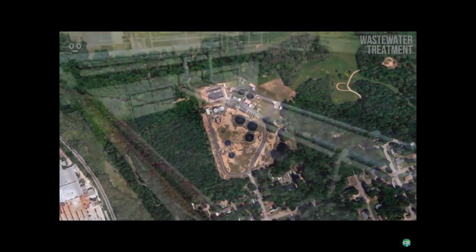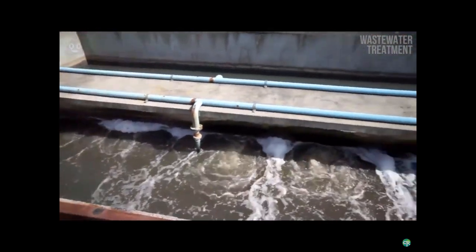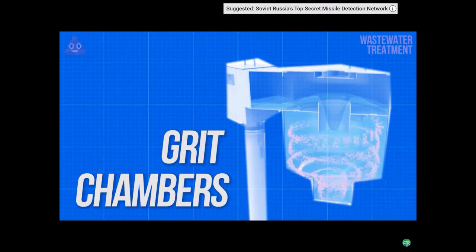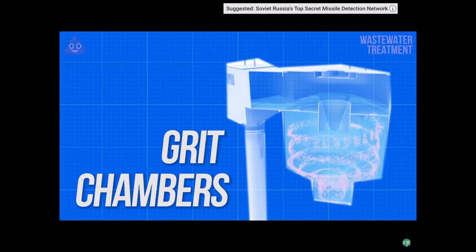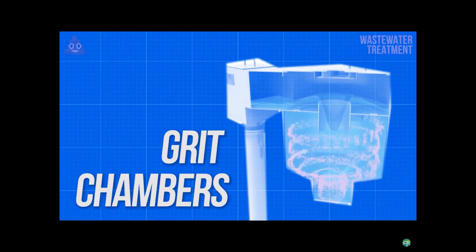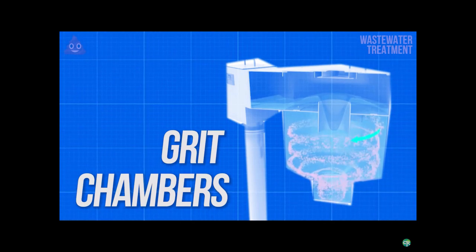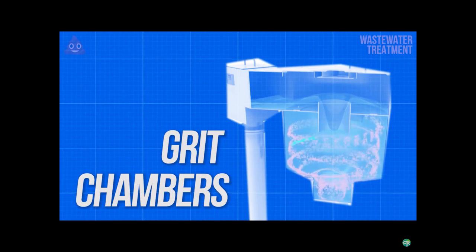Since these bars don't catch everything, the next steps in the pre-treatment process are grit chambers. Larger particles called grit still need to be removed from the sewage. As the sewage flows into the grit chamber, the velocity of the sewage, which is viscous, is adjusted to allow the particles of sand and rock to settle out. This is needed because these particles can't be removed using chemicals, and they could potentially clog or destroy pumps later on in the process.